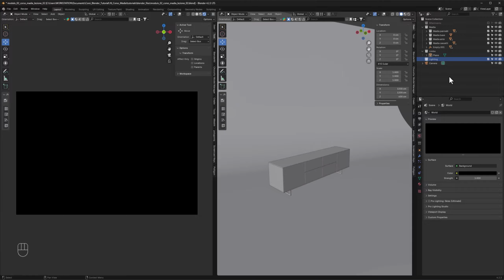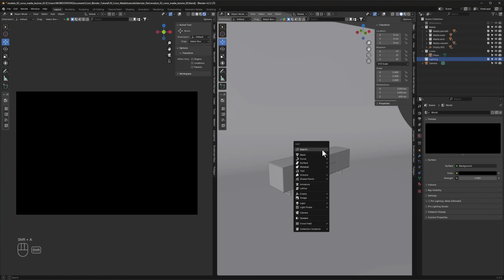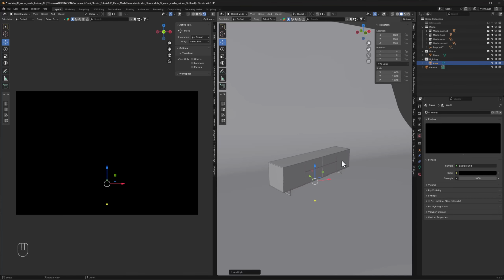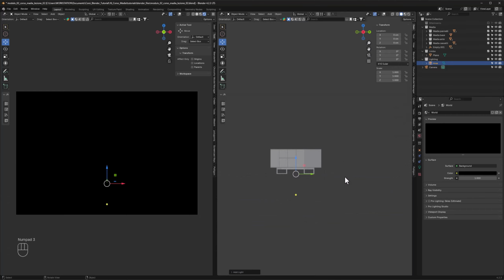In the Perspective window, press Shift+A, click on Light and then select Area. Press the 3 key on the numeric keypad to switch to the right side view. Also set the display mode to wireframe. This will allow us, with the backdrop's profile clearly visible, to better position the light source. With the area light selected, set the Y and Z values of the location parameter to 200 centimeters.